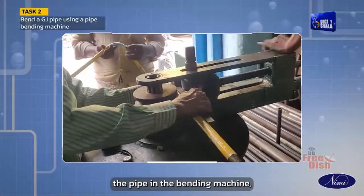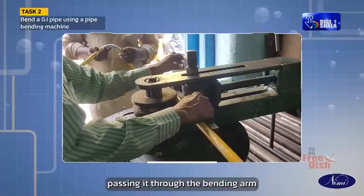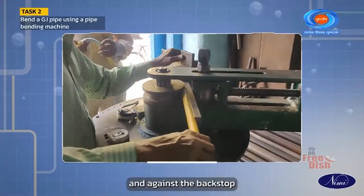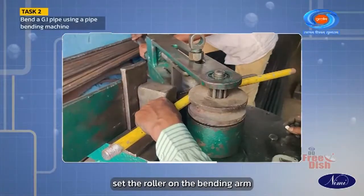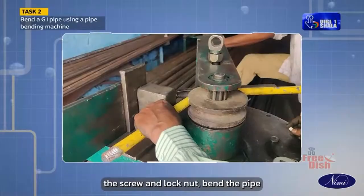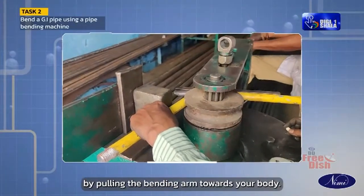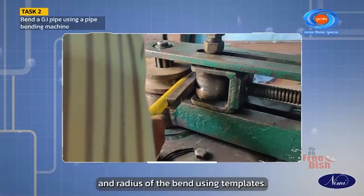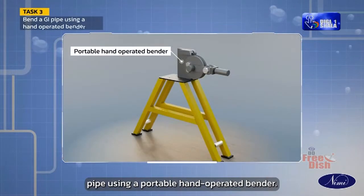Place the pipe in the bending machine, passing it through the bending arm and ensuring that it is seated within the groove of the former and against the backstop. Set the roller on the bending arm by adjusting the screw and lock nut. Bend the pipe by pulling the bending arm towards your body. Check the angle and radius of the bend using templates. Let us bend a GI pipe using a portable hand-operated bender.